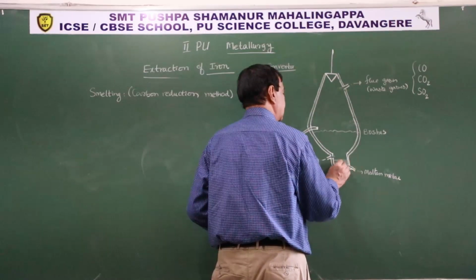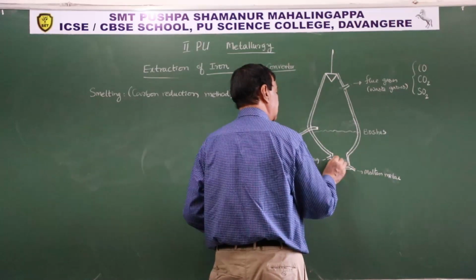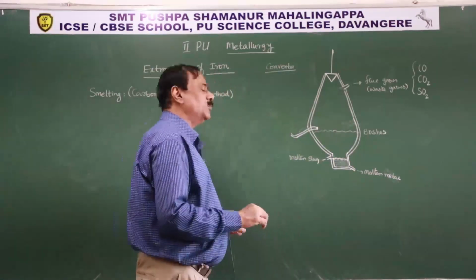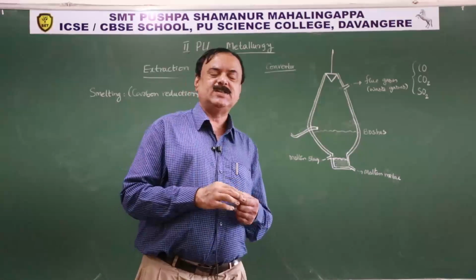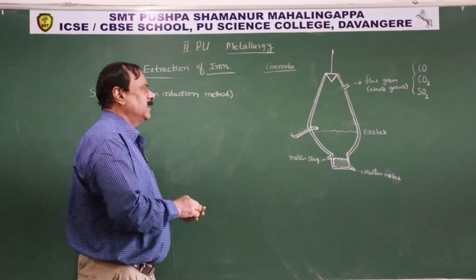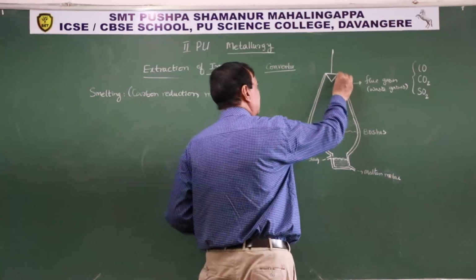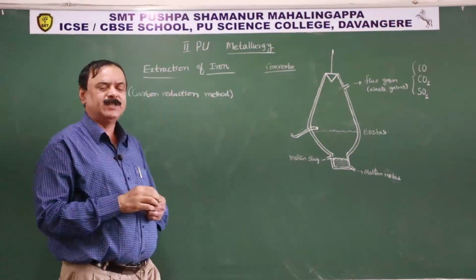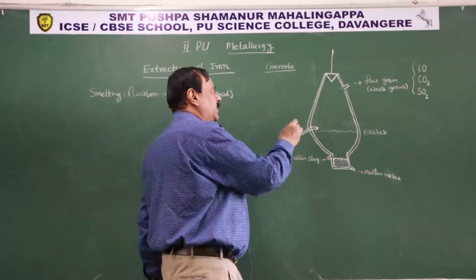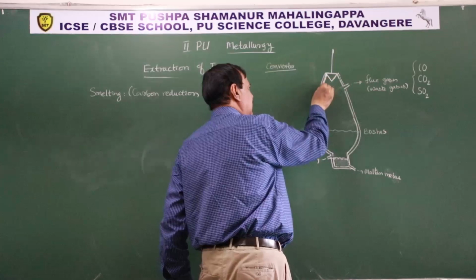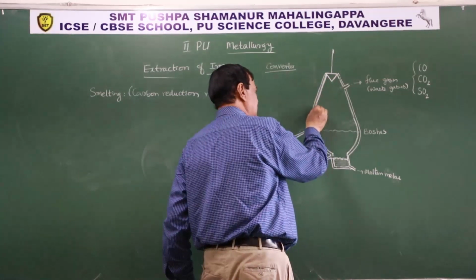This is for the removal of the molten metal. The upper layer is for the slag layer that protects the molten metal from atmospheric oxidation reaction. Now, very important, the furnace is provided with one water cooled pipe in order to avoid loss of heat due to radiation. The inner surface of the furnace is layered with fire resistant bricks.